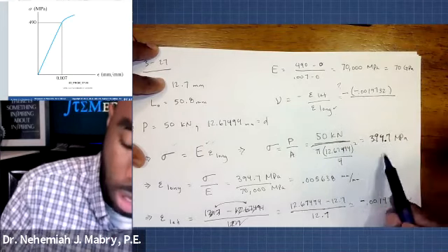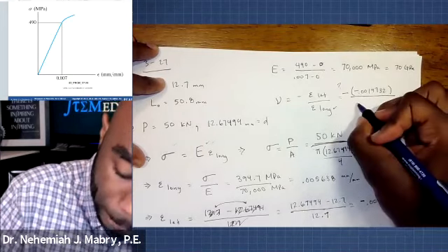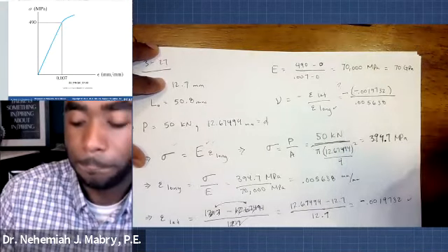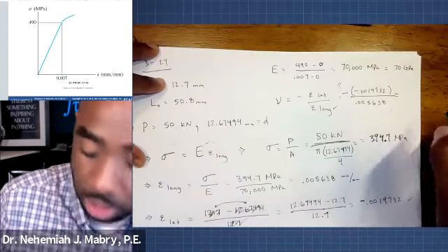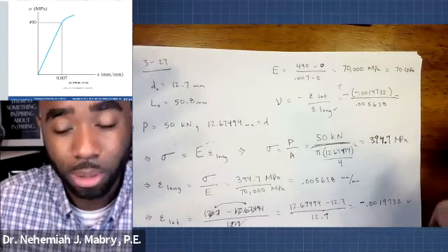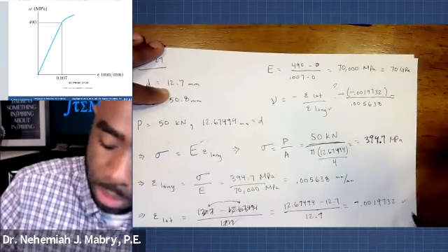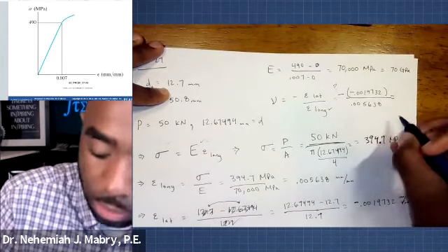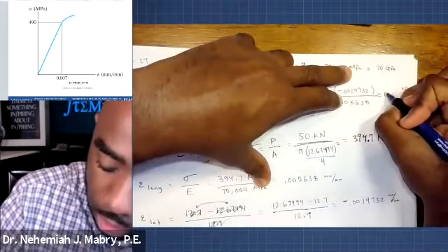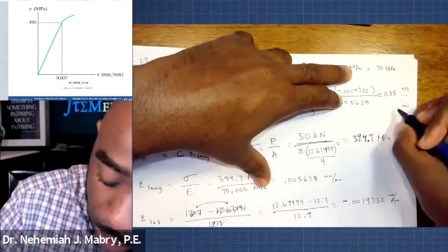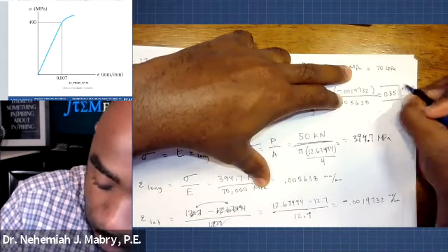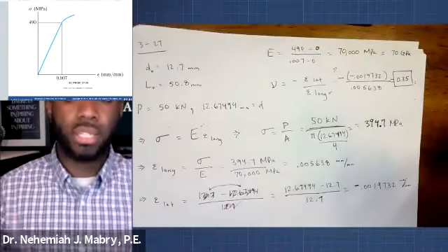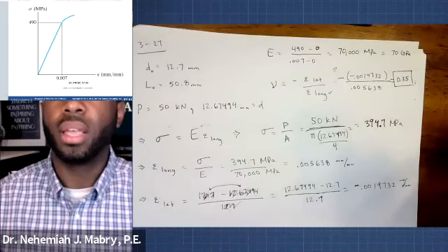over E long, which we found here to be 0.005638. And now we can calculate this here to get the answer. This is a ratio, so it shouldn't have any dimensions because both of these numbers are dimensionless, or millimeters over millimeters. And if your calculator agrees with mine, it should be 0.35. That, according to the problem, is our Poisson's ratio and what we were solving for.